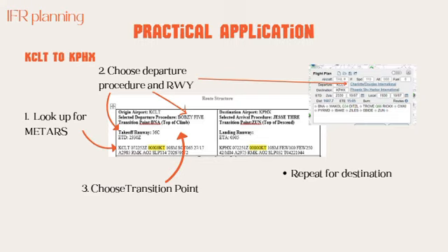We have calm winds and 10 miles visibility at our departure airport, ensuring a smooth takeoff. We choose the departure procedure chart that will be BOPSI 5. With this, we know the runway and the airport information. We will use runway 36C as it is the longest runway, and it ensures that we will not have to deal with wind interference. Third, we choose the top of climb, or transition point, which will be BNA, that is the Nashville VORTAC.